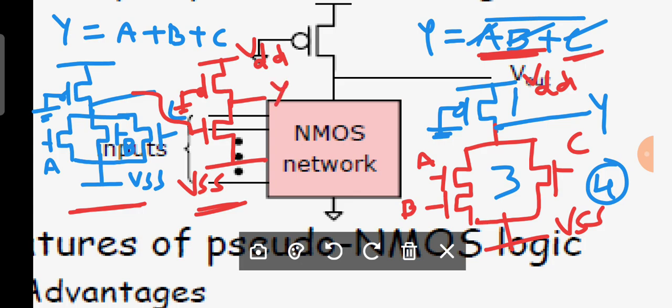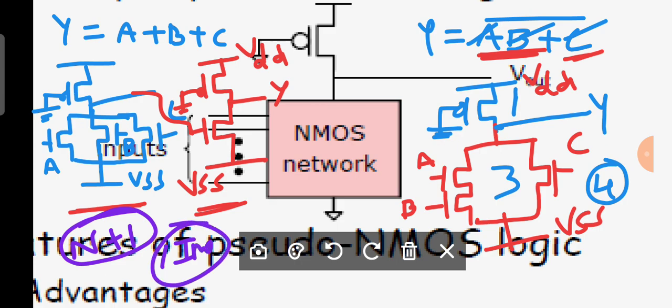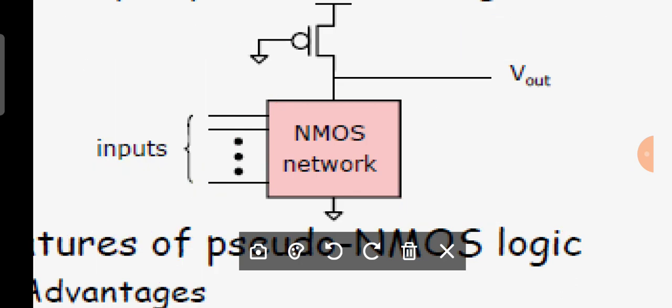Is it understood? When there is no complement, then the very important point is you have to tell n plus 1 transistors. Okay, I will write some other way, with some other color. You can observe that n plus 1 transistors are required, followed by one inverter. That is an important point you have to talk about. Is it understood? Now will you please tell me what are the drawbacks present here?